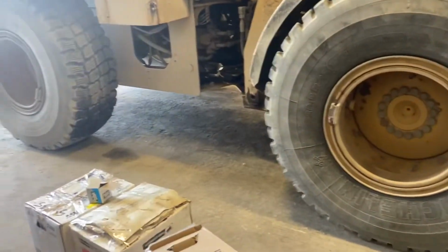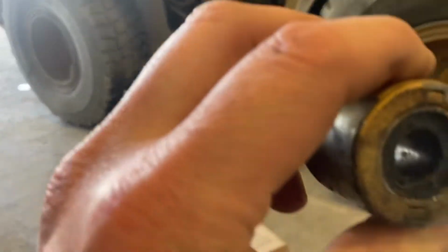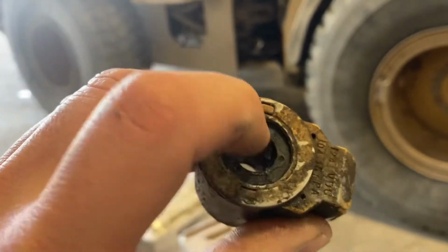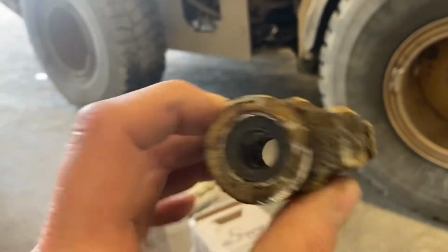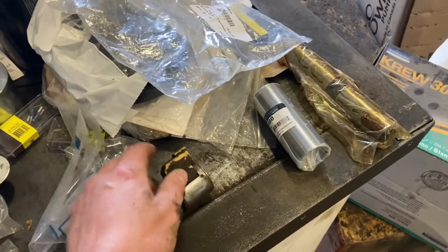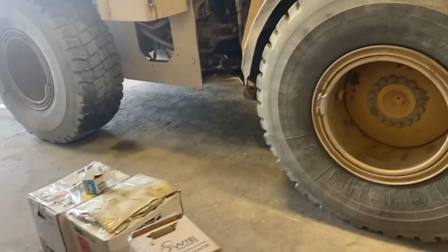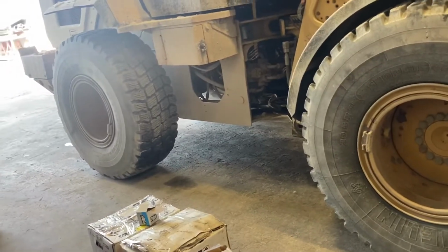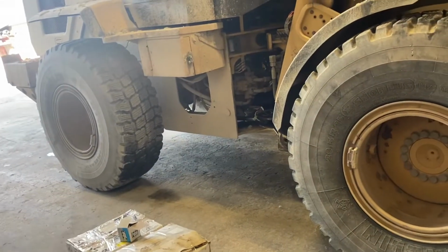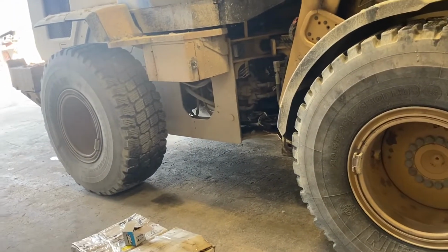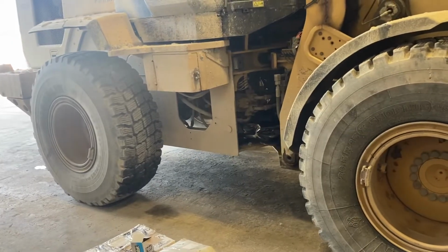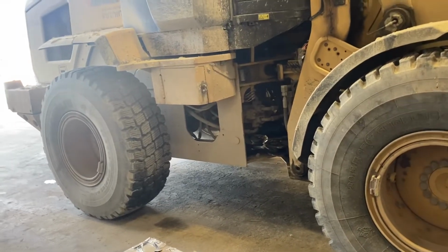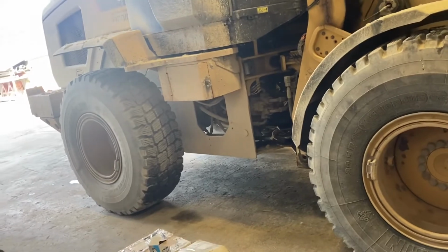But one thing that I've found too is this one's pretty good, but inside here you'll get corrosion between the solenoid coil and your valve, the hydraulic valve. When that happens, that can cause too much resistance and it seems to cook the solenoids. So just because it's really hot doesn't necessarily mean that's how you diagnose it. You're still going to do resistance checks and voltage checks and ground and all that. But that's just one of the signs. That's one thing that's going to help you diagnose it: it's going to be really hot.